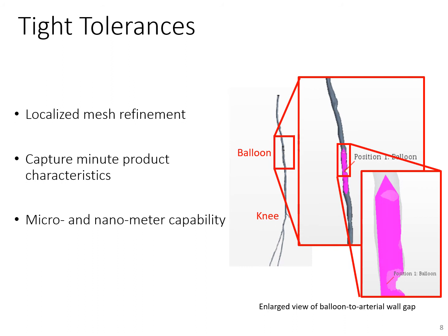The example shown here was part of a study looking at drug-coated balloon angioplasty deployments in the human leg and evaluating the effect of the size of balloon inflation on the distribution of the drug as it washed off the balloon and flowed downstream. The typical procedure for this particular balloon angioplasty called for the balloon to be overinflated to open the vessel and then deflate the balloon slightly to allow the blood flow to begin to wash over the balloon. The balloon to vessel distances on these simulations range from 0.3 of a millimeter all the way down to under 1/10 of a millimeter.